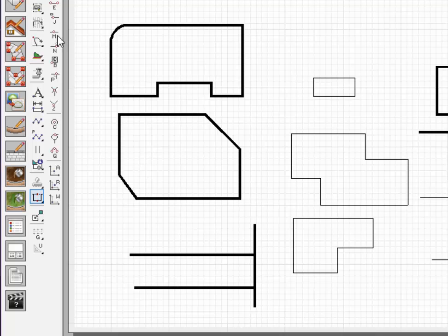Okay. Also with the alcove tool, we can go up to the edit bar and we can change the angle of the side walls here. So I'm going to change it to a 45-degree angle, and I'll create an alcove here. I'll click on this line to select it. I'll click on the point where I want to create the alcove. Okay, I set the width of the alcove, and I pull that up to set the height or the depth, and I click, and that creates an alcove with 45-degree sidewalls. Okay, and that is our trim tools.